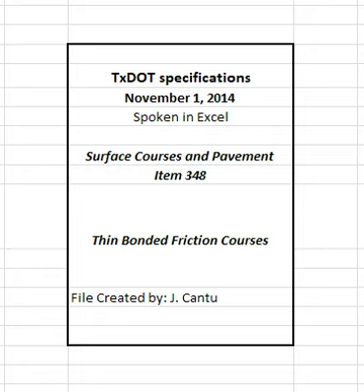Calculate the daily yield and cumulative yield for the specified lift and provide to the engineer at the end of paving operations for each day unless otherwise directed. The engineer may suspend production if the contractor fails to produce and provide haul tickets and yield calculations by the end of paving operations for each day.